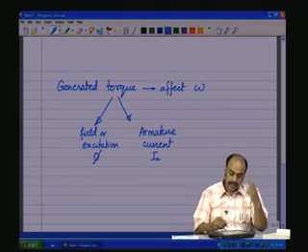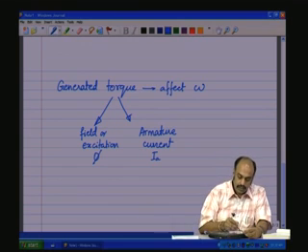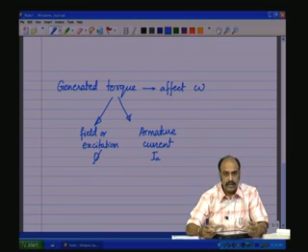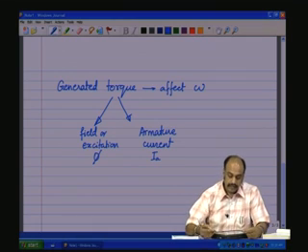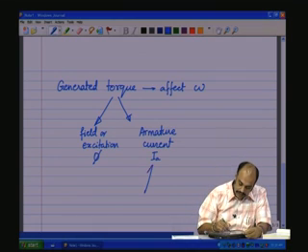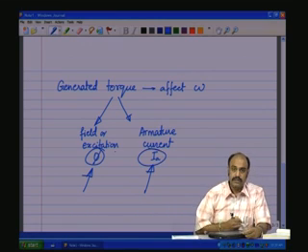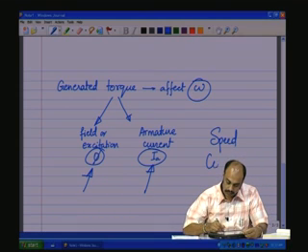So, by controlling the armature current IA or the field or excitation phi, or both, one can control the generated torque, and for a given load that is going to change the speed. This means that the speed of the DC motor can be controlled by controlling these two parameters to achieve speed control.